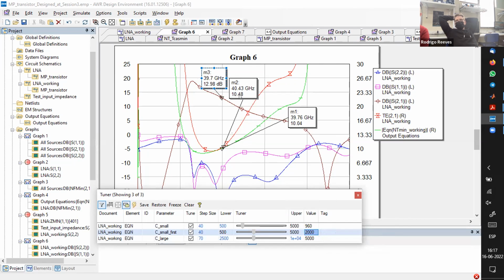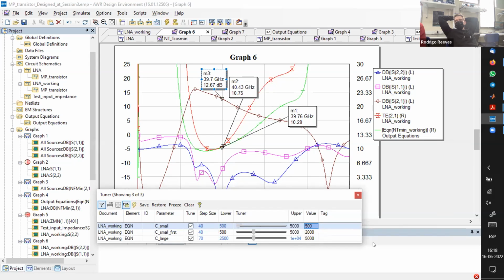The first capacitance is affecting the noise directly, so it needs to be large enough. Once you have gain from the first transistor, you can use the others. They can be even smaller, 0.8 or something. Now it's getting better, but you already see that you're affecting the noise. So between 1 and 0.5 picofarads, I would put that.